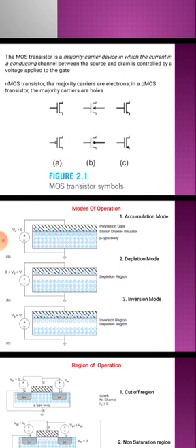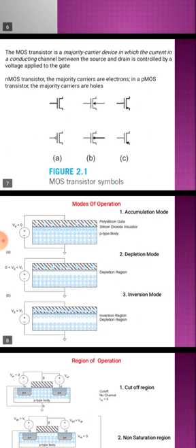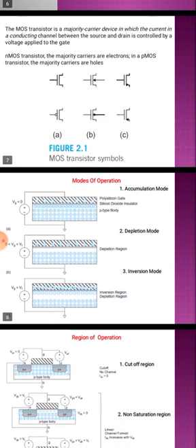Now let us discuss NMOS enhancement mode MOSFET. Here in this presentation, the symbolic representation of MOSFET is given. For the N-channel MOSFET, there is no bubble in the gate terminal. N-channel usually comes without a bubble. P-channel MOSFET comes with a bubble present in the gate terminal. Or we can use alternative symbols for both P-channel as well as N-channel MOSFET.